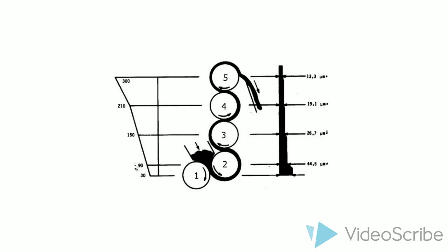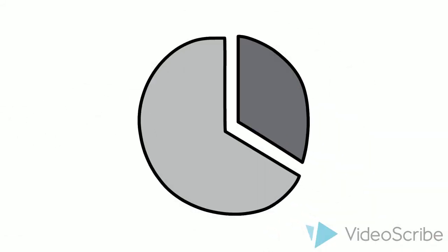The chocolate is attracted to the rollers by lipid and fat particles that remain on their surface, causing the chocolate to form a thin film. The lipids also absorb undesirable volatile compounds in the chocolate. The particle size distribution can be measured by laser diffraction. The distribution in the chocolate also has an important impact on the viscosity of the product. Studies have shown that a 60 to 40 ratio of coarse to fine particles generates the lowest viscosity.